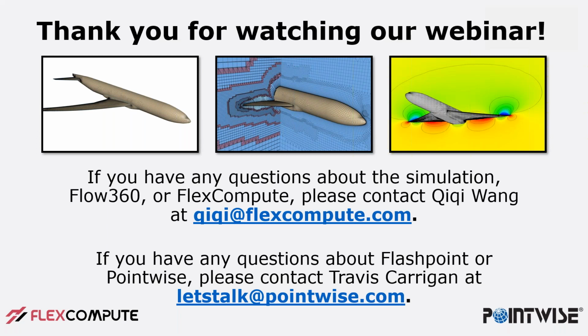If Flashpoint produces a mesh with quality problems, are there any tools to improve it? Yes. When you make a mesh using Flashpoint surface meshing, inside that tool you can look at grid quality. While you're in there, you have the resolution controls at your disposal, including local resolution controls, to modify or refine the surface mesh.